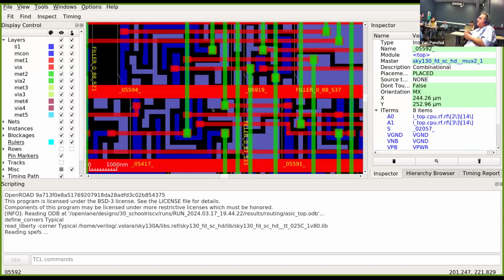Synthesis of a block like mine takes several hours, but the whole thing takes a day or two. So the whole large thing does take some time, but after you synthesize and run all the design checks, you need to send it to the foundry to make a set of masks. This is a very expensive operation.